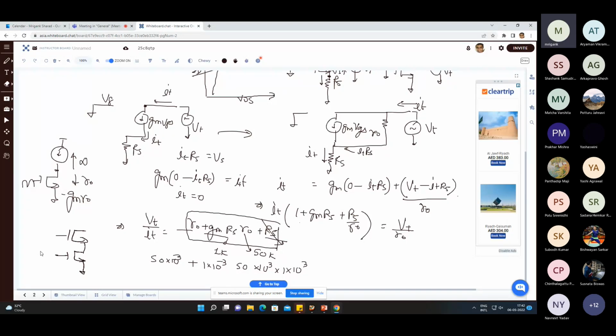So this is VB, a constant voltage, and this is another VG. And then you are trying to look into the drain of the MOSFET. So if I say, okay, what is the impedance over here? Here, what is RS? This is also similar. The only thing is the source resistance I have replaced by a MOSFET with a constant gate voltage. So what is RS? It is the RO of the lowermost MOSFET. If I call it M2, and this one M1, in this case RS is nothing else but RO2.